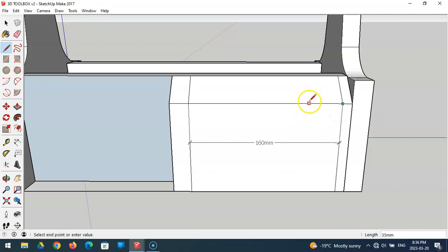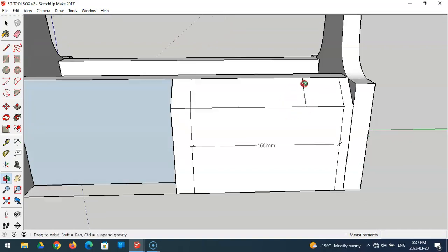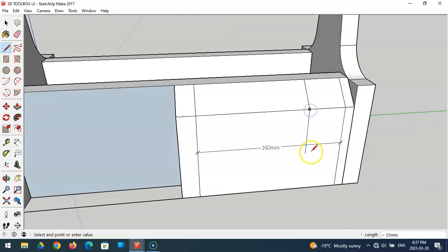So let's go like this. Drop this on 40, type in 40, find 40, come up so this is parallel. Yep, that's nice. Then we're going to come down all the way to the bottom. Now I'm going to go to the left 20. Nope, that went the wrong way. Control Z, let's try that again. All the way down, then to the left 20. I've got to find that point. I'm going to come up, click here, and then parallel. There, it snapped to parallel. Now let's see if that worked.